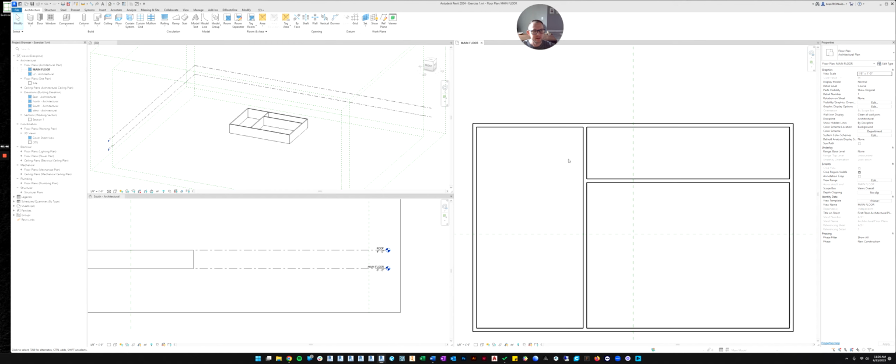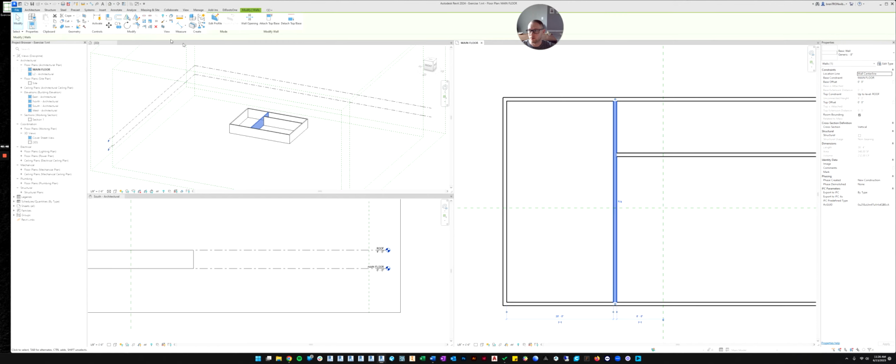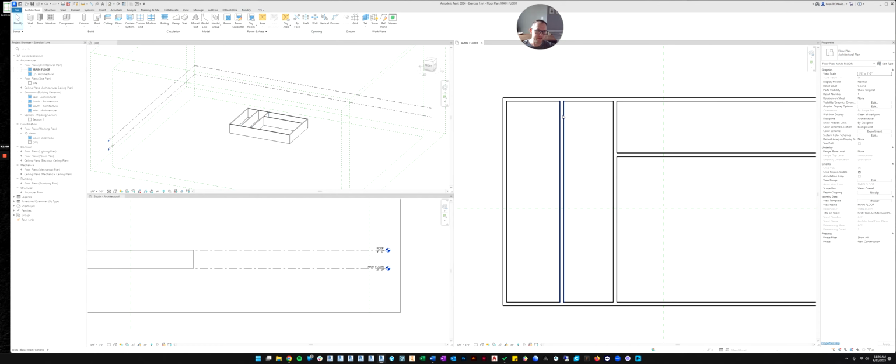Also, copy is pretty common. So let's select a wall. If you go over here, there's the copy command. If you click it, it allows you to pick 2 points again, a reference point and then the destination point. So we can click the wall, and if we want it to be 10 feet away, we can do like we've been doing before. We can just set the direction and type in 10, and it copies the wall 10 feet. So I'm going to delete that.